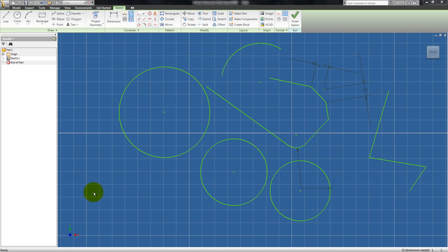One thing I forgot to mention that is perhaps very useful is selecting and deleting drawings. If you click and drag, you make these selection boxes. This quadrant is different than this quadrant visually, but it also selects differently. If you select down and to the right, anything that is completely contained will be selected. So the circle now will be completely contained, and it is the only thing that is selected. If you want to delete drawings, hit the delete key, or you could also select them just by clicking them.